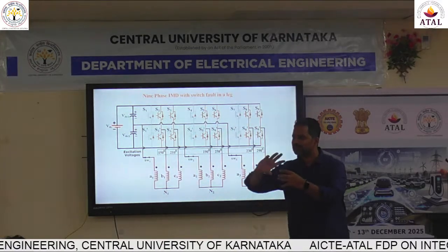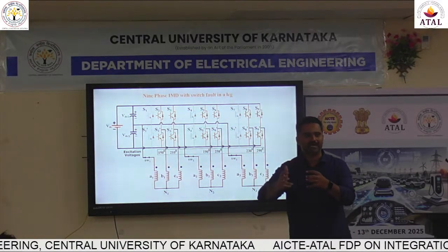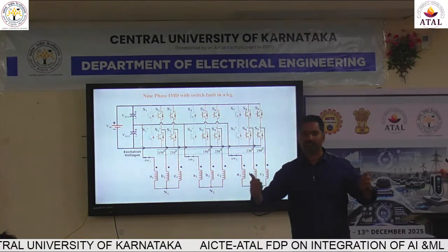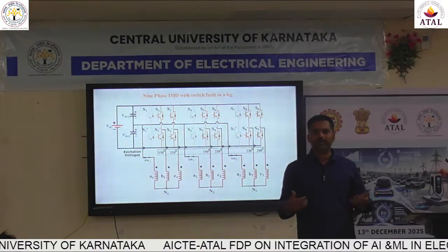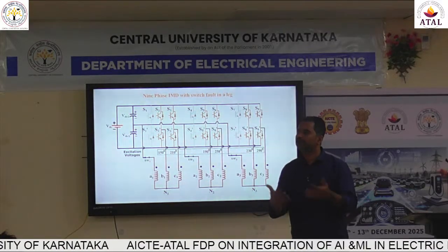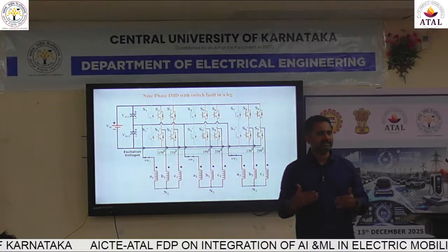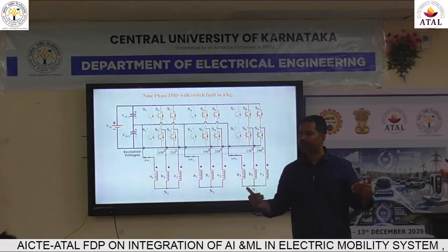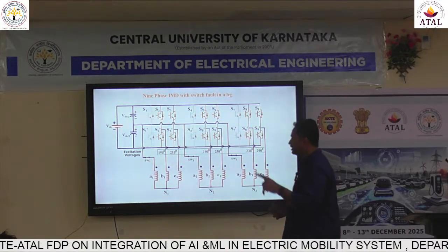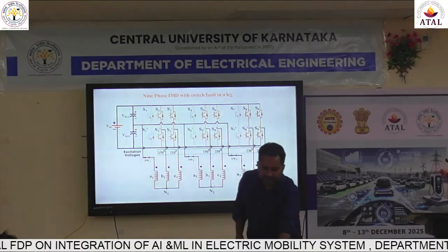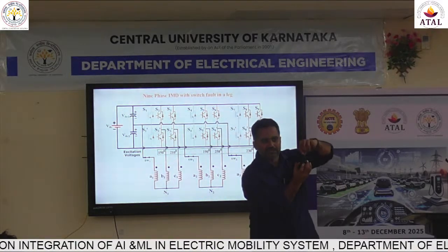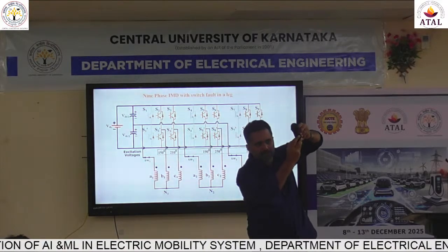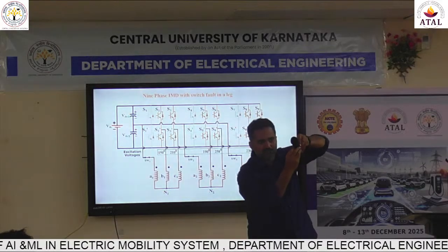Similarly, in the vehicle, the shaft has different forces, and if the forces are not balanced, that translates to the bearings, because of the imbalanced shaft, and the bearings will collapse. You go back and look at the fault scenarios, bearings are one of the major culprits in failures. The reason is that when you don't have equal forces on it, any imbalanced forces will translate to the bearings, and the bearings can fail. So that is the reason I have to maintain symmetry. Whatever force reduction happened on the shaft, the same amount of force reduction has to happen at 180 degrees. If both were pushing on opposite sides, both have to be equal. Otherwise, what will happen?